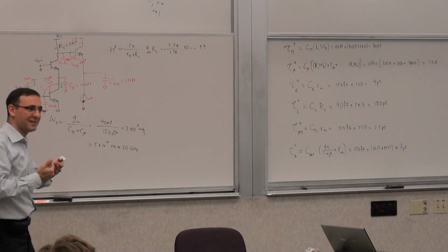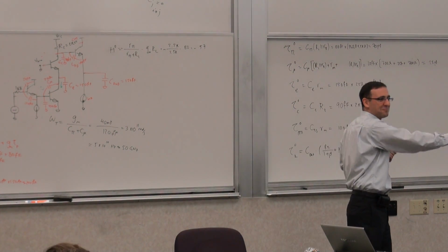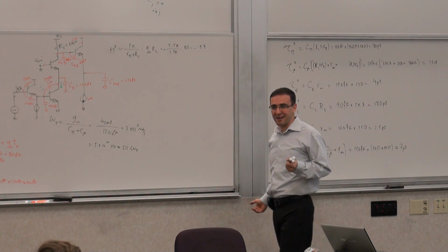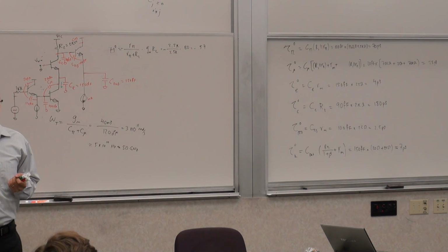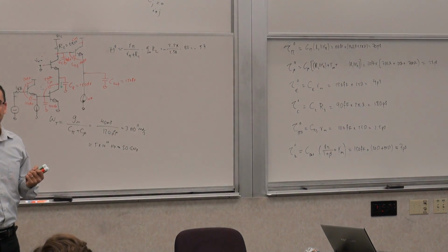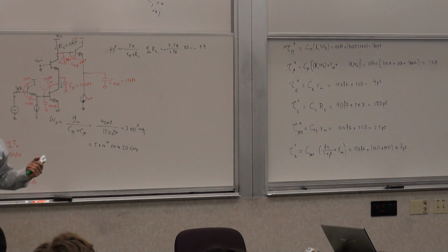If you put an infinite number of stages with 1 plus epsilon gain back to back, that's not going to have very good bandwidth because it has infinite poles. It has a lot of poles. So there's an optimal actually. We can calculate it, and we'll do some of that next quarter. But I can give you the answer.